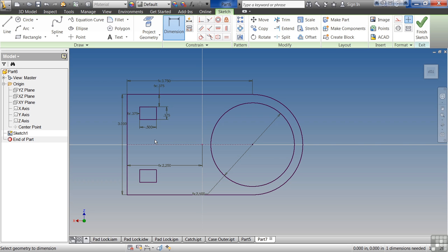Remember, capture it early, capture it as simple as possible, and you want to capture the constraints before you capture the dimensions. Basically, what shape should it be before what size should it be? And if you notice, the very last thing we do is the size. AutoCAD users, this is the opposite of what you're used to, and this is very hard for you to get used to. But sketch it out very roughly.